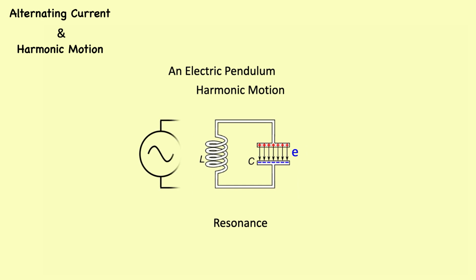If a power supply frequency for a circuit exactly matches the natural frequency of the LC combination, the circuit is said to be in a state of resonance. The unusual effects will reach maximum in this condition of resonance. For this reason, we need to be able to predict what the resonant frequency will be for various combinations of L and C and be aware of what the effects of resonance are.